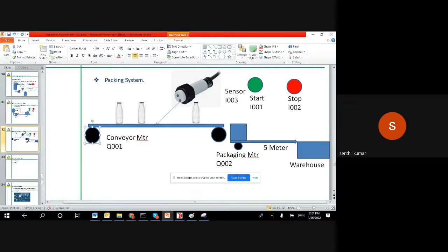When I push and release, I can set the conveyor run, that's my first thing. And if I am stopping it, yes, it has to stop. Set, reset, flip flop can start and stop this.